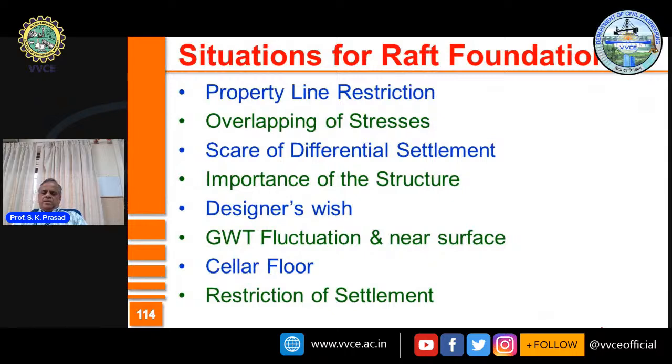Okay? Well, I can speak now on the situations which promote a designer to go for raft foundation. All those situations which promote the designer to go for combined footing hold good here. In addition, you need to consider perhaps the effect of the groundwater table, perhaps the underground cellars, or maybe the settlement criteria. Probably we will discuss this in my next class.